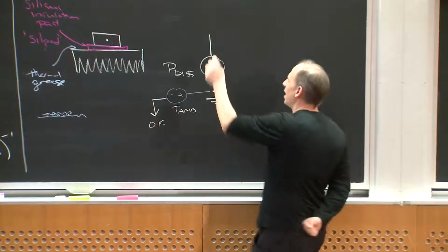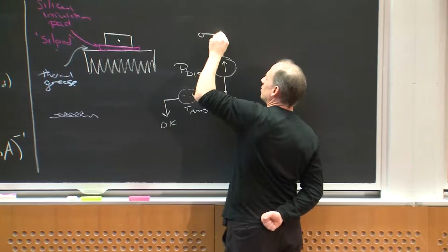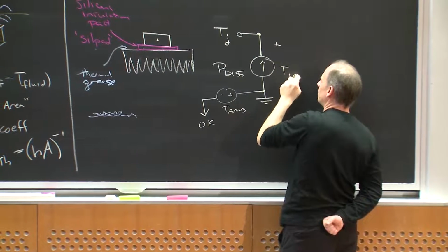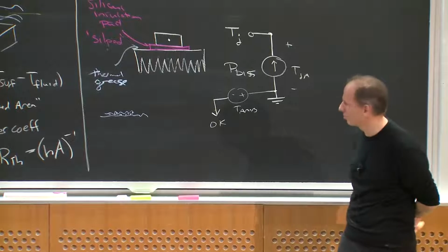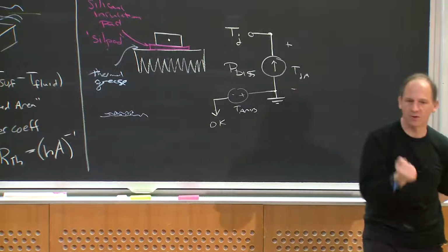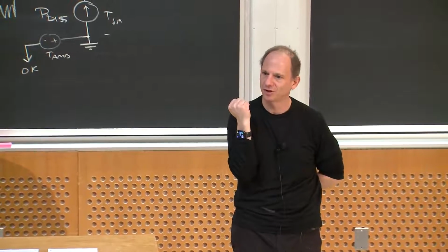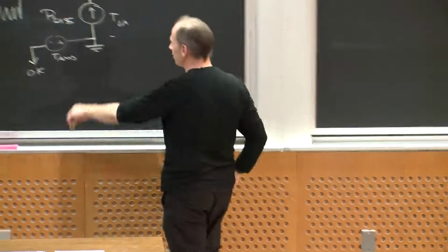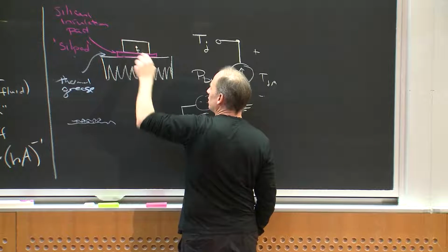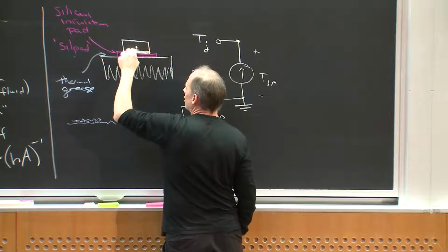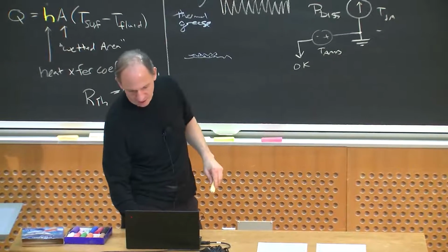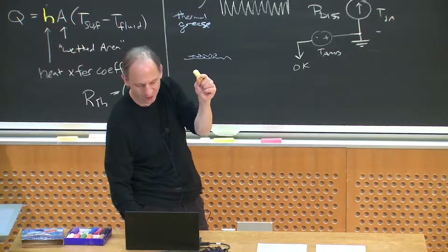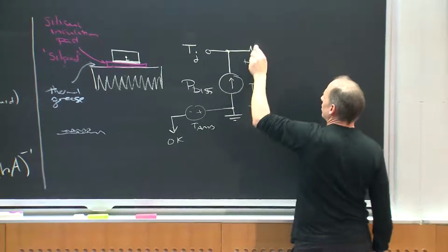That's the power dissipation, and we often say this temperature is at T junction, right? So it's either, this is T junction to ambient or T junction absolute, depending upon how I decide to write this. The junction is just my notion of wherever the power is being dissipated in the device. It may be an actual physical semiconductor junction. It may just be wherever in this device is where the heat's being dissipated. Okay? Then I've got to transfer the heat to the surface of the device, right? Because I said, the heat's actually being dissipated inside, and there's some thermal resistance between where the heat's being dissipated inside the semiconductor to the actual case.